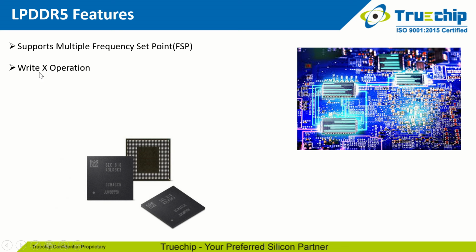As all previous generation LPDDR DRAM devices support write operation and multi-write operation, LPDDR5 comes with the addition of WRX operation, as this write operation reduces the power consumption in case of repeated data patterns. It can be operated to an activated bank without WCK to CK synchronization and data input to SDRAM DQs. But it doesn't mean that it doesn't work in case of WCK to CK sync state.